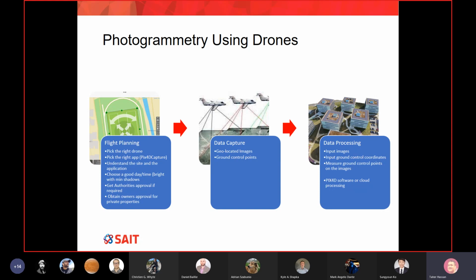I need to remind everyone that in photogrammetry, it's not really random images. We're not taking random images and creating a 3D model. The images must meet specific geometry in terms of overlap. If the images have no overlap, then I'm screwed. I'm just going to throw them in the garbage. If my images have a specific overlap, then I can use them to build a 3D model.